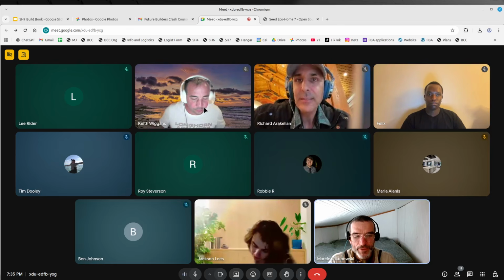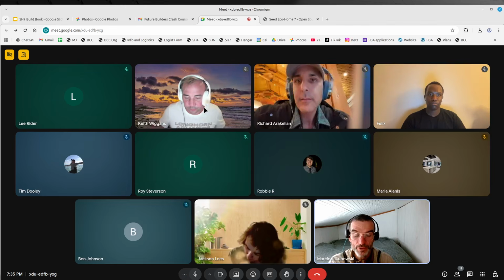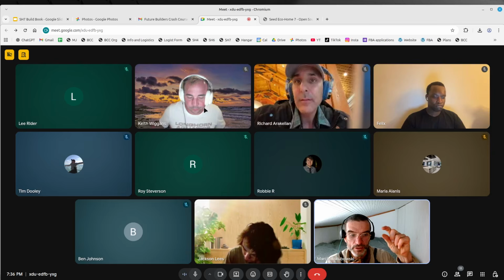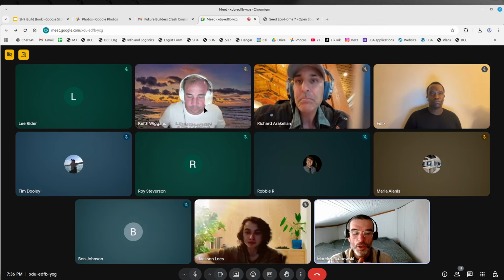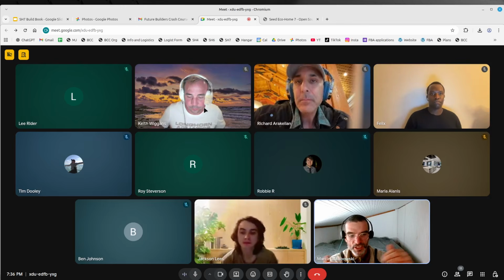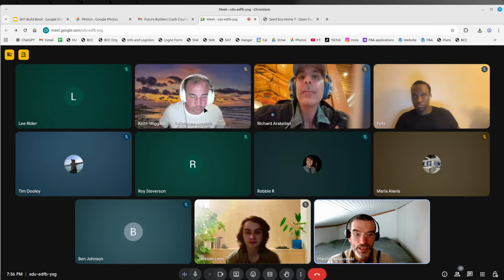On top of that is gravel. So the gravel is important for the purpose of preventing any UV degradation. In UV it will last like 5 years, 5-10 years maybe. It's black, so it's got UV inhibitors, but that thing just doesn't last. For lifetime design, you're like 50 or 100 years. So if you bury that with some gravel, just a little layer, inch or two, you got no UV degradation. All the joints, including like the sides, are trimmed up, so there's no UV actually hitting that membrane, and that makes it a very long-lasting roof.